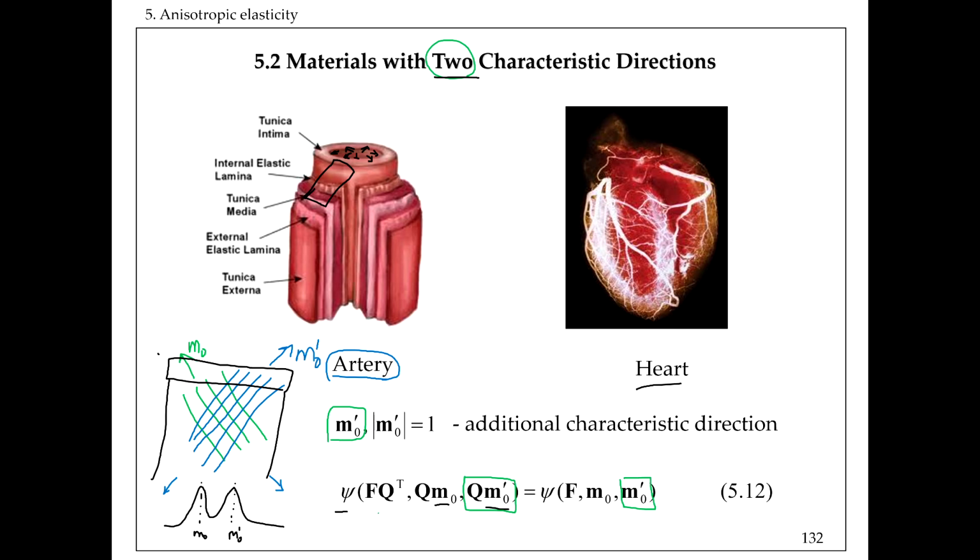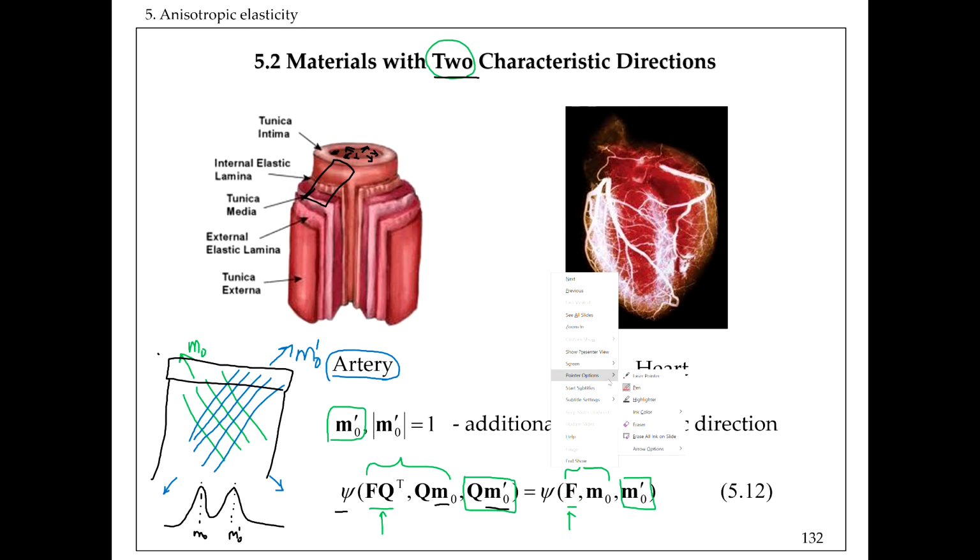And therefore, when we had only these terms sitting here, the first is common for isotropic elasticity, no fibers, and the second one is with the first orientation here. So this is just one family of fibers, all the fibers aligned in one direction. And now we can say that we added additional fibers, if you like, and they are now aligned in a different direction, M tag here.